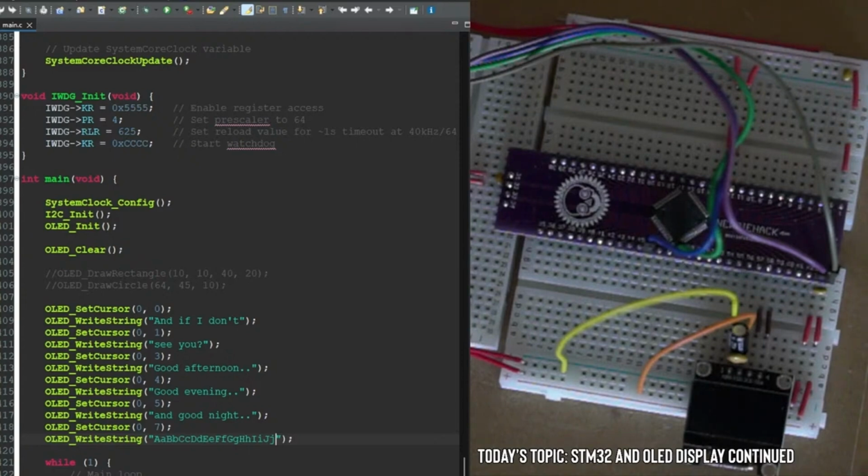No, there is a mode of USARTs that apparently allows lots of devices on one bus, each having its own address, kind of like I2C, but based on USART. Yeah, and also there's the servos that I have by Dynamixel. They also do the same thing. They have their own IDs, and they use the same USART, and you have to put them on the same line, which is kind of interesting. So you can have like 255 servos.